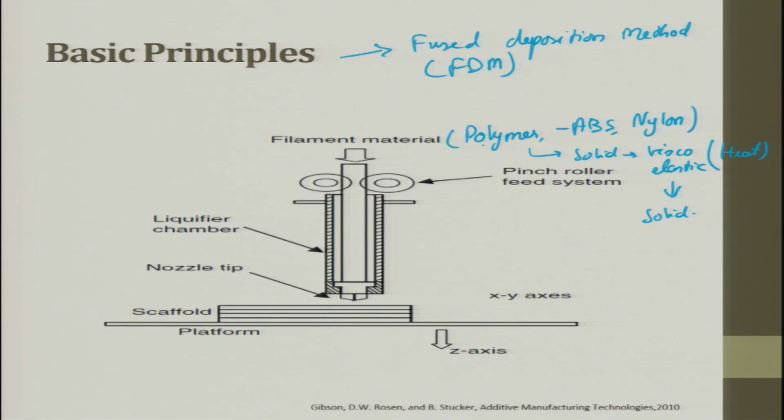So, filament is there, polymer, you can also use metals. Today we are talking about metals, where people are trying to use copper, aluminium, steel, okay, steel rods are used, they are passed through a nozzle. Okay. So, in order to have a proper tension, constant pressure of feeding, we use this pinch roller. This is for constant pressure. You remember in the cake icing example, we talked about constant pressure.